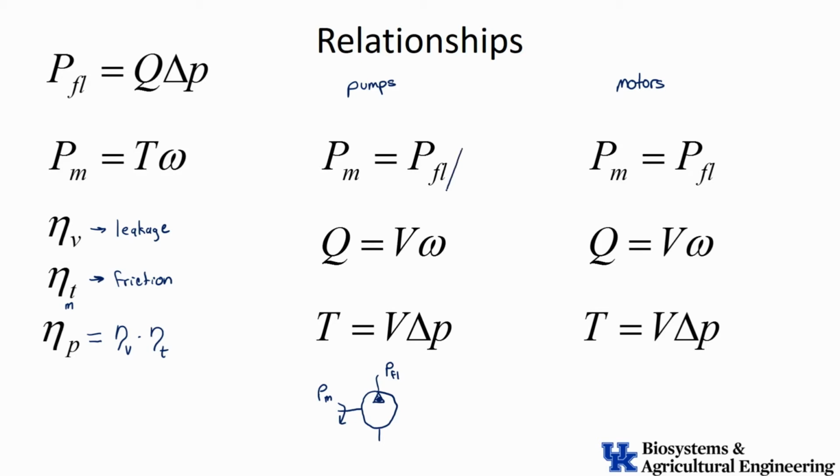So what I need to do is divide that by the power efficiency. So I'm going to put the power efficiency in the denominator. I divide by a number that's less than 1. These efficiency numbers are all a fraction of 1. I divide by a number that's less than 1. That makes that overall a bigger number, and it matches that mechanical energy. It shows that the mechanical power is a little bit bigger. Okay? Likewise, let's go through the flow rate equation.